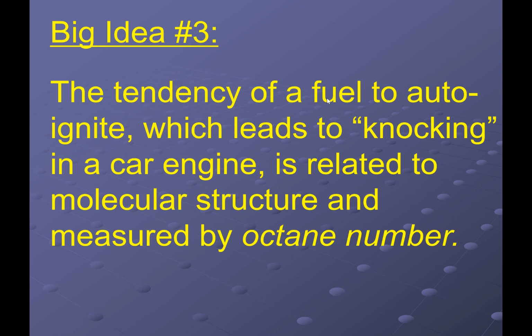Some fuels are prone to what's called auto-ignition. Auto-ignition meaning even without the piston, without your engineering and things like that, it just tends to catch fire, it just tends to burn on its own. Obviously, that already becomes a safety hazard, but more so, your pistons may not be maximally spread out, and maybe the fuel has already burned, and it's not actually delivering the amount of energy that your engine was designed for. This tendency to auto-ignite is typically called knocking. It tends to actually make a knocking sound from the engine. That's why it's called knocking.